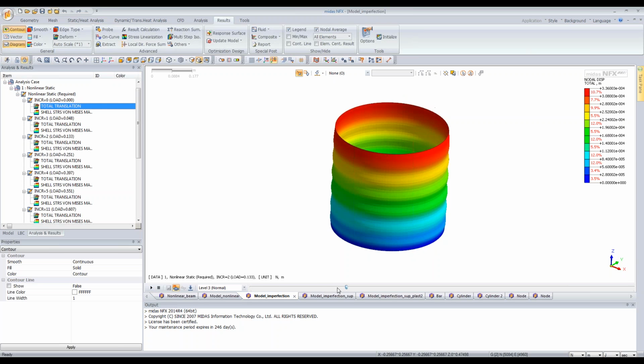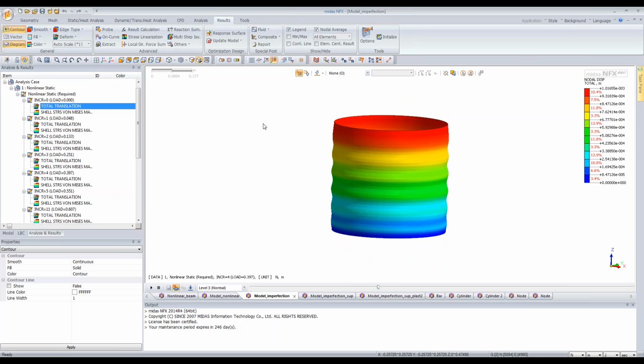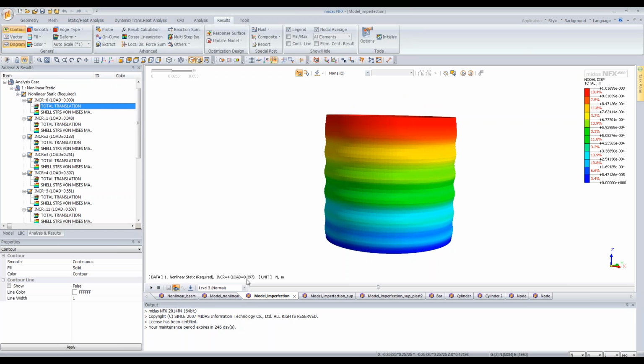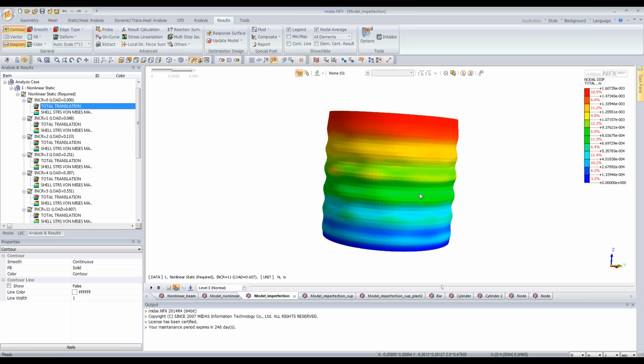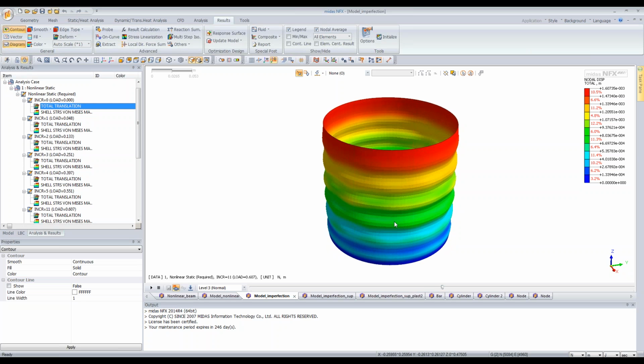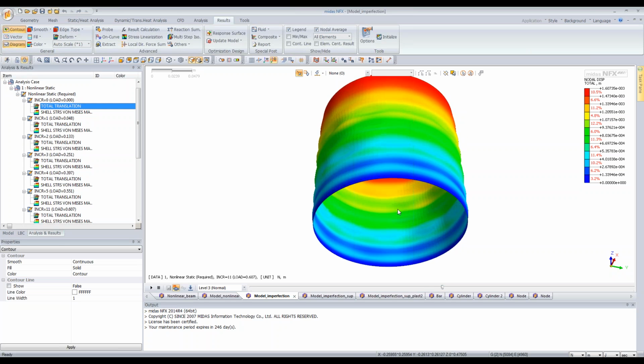So what is important? For this stage, which stands for the 0.4 total load, we are still observing the first eigenvalue, but close to 0.5, so 0.551 is the last increment where we are seeing the eigenvalue, and after that the structure starts to have some bubbles, and a different path of stability is provided.